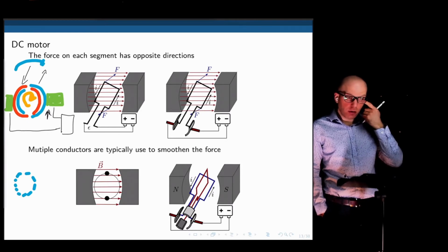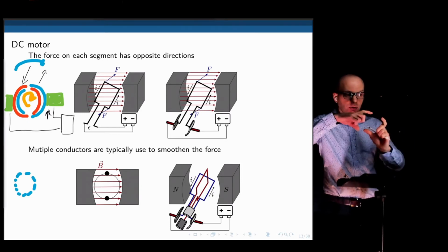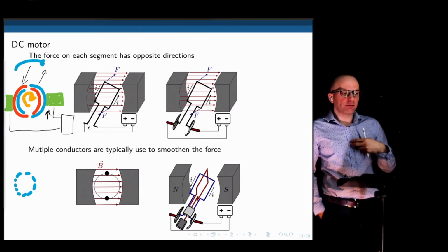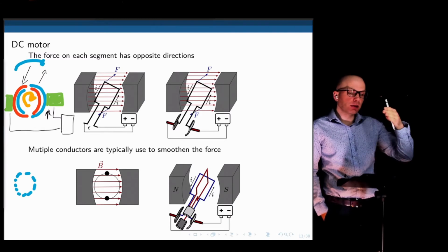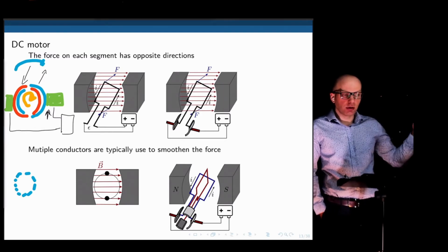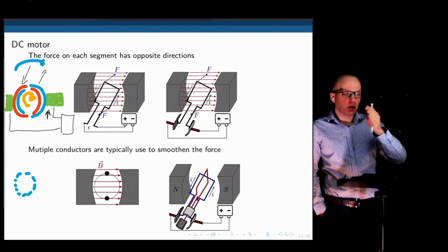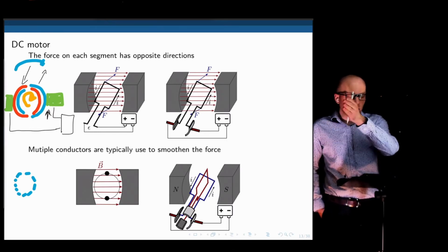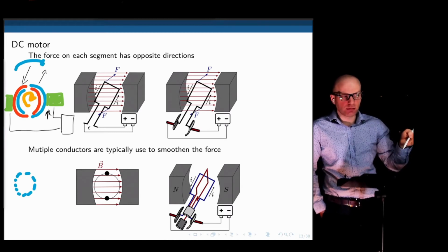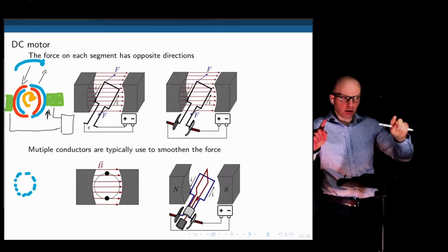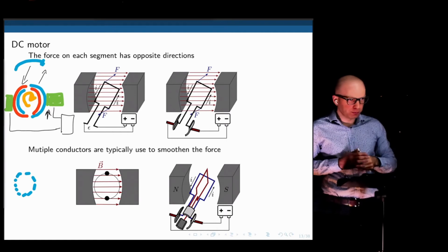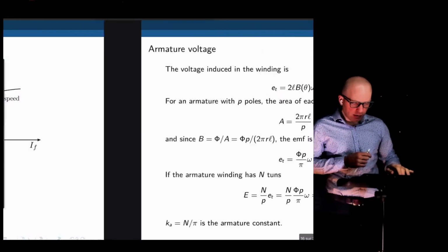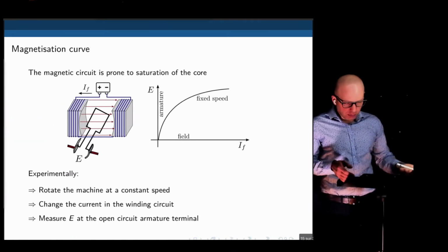They are always fixed with respect to one another, they're just rotating. The blue one touches the right collector during half a cycle, and during the other half cycle, the blue touches the left connector. When the blue touches the left connector, the red one will touch the right one immediately, and they stay that way for half a cycle each. If that's not clear, I can try to explain that during office hours in more detail.